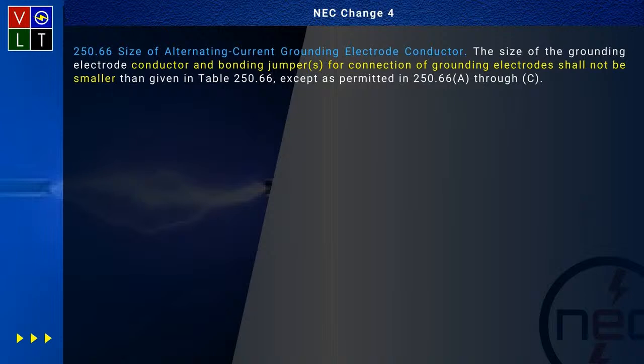if you have a 100 amp service, which I've never installed before, but you have a 100 amp service, you could take a number 8, you could call it a grounding electrode conductor. Then you have 2 grounding electrode conductors. You have the grounding electrode conductor from your service to connect to the grounding electrode conductor to your building, to your concrete encased electrode. I mean, that's fine. You have 2 of the same exact things, but the minimum size for the concrete encased electrode is still a number 4 that doesn't change based on a 100 amp service. That's right. It sure doesn't.